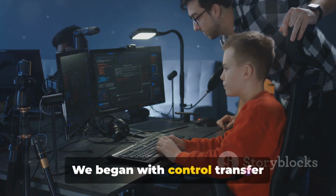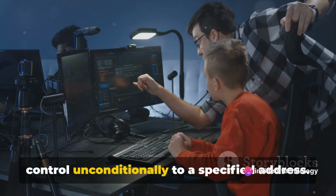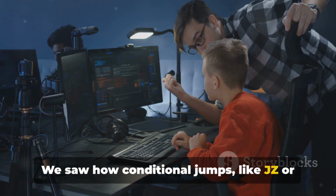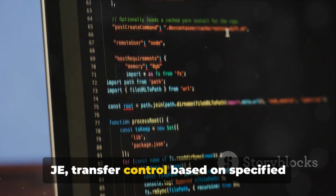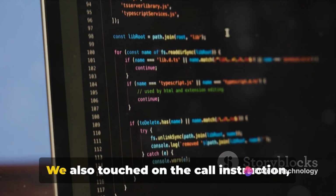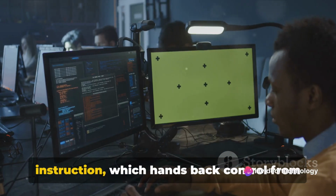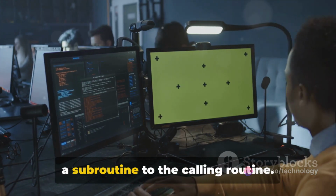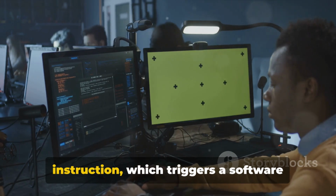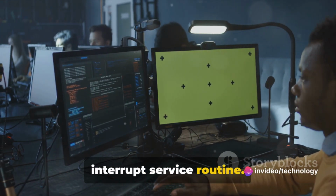We began with control transfer instructions, starting with the unconditional jump, which transfers control unconditionally to a specified address. We saw how conditional jumps, like JZ or JE, transfer control based on specified conditions like zero, equal, and more. We also touched on the call instruction, which calls a subroutine, and the return instruction, which hands back control from a subroutine to the calling routine. Lastly, we discussed the interrupt instruction, which triggers a software interrupt, transferring control to an interrupt service routine.